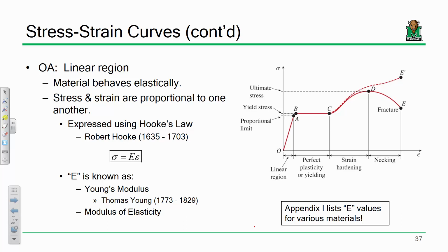If they don't behave elastically, then the flip side is that they behave what we call plastically. So there's elastic behavior and plastic behavior. And plastic behavior is a lot like a Coke can. If I have a Coke can in my hand and I crush it and I let it go, it's not going back to a perfectly smooth Coke can. It's going to remain crushed, right? So imagine if something like that happened with these floor beams up in this floor system. People walk on it and they remain sagged. Then you put more load on it, they sag more. The building is not behaving the way that we want it to.